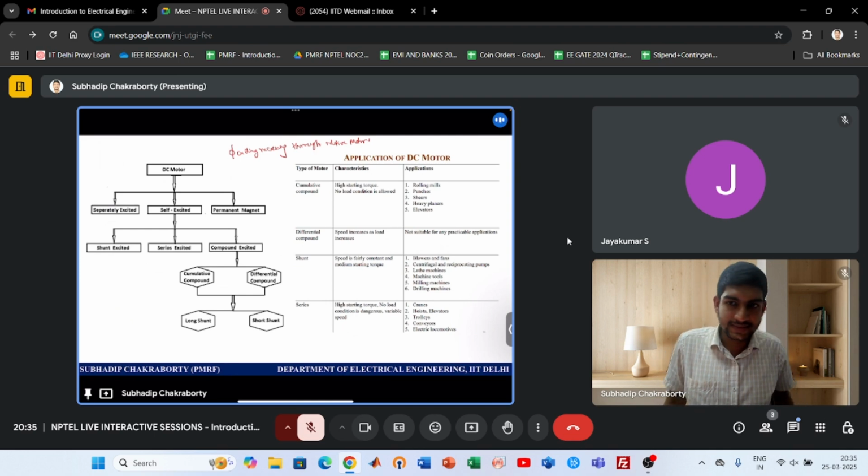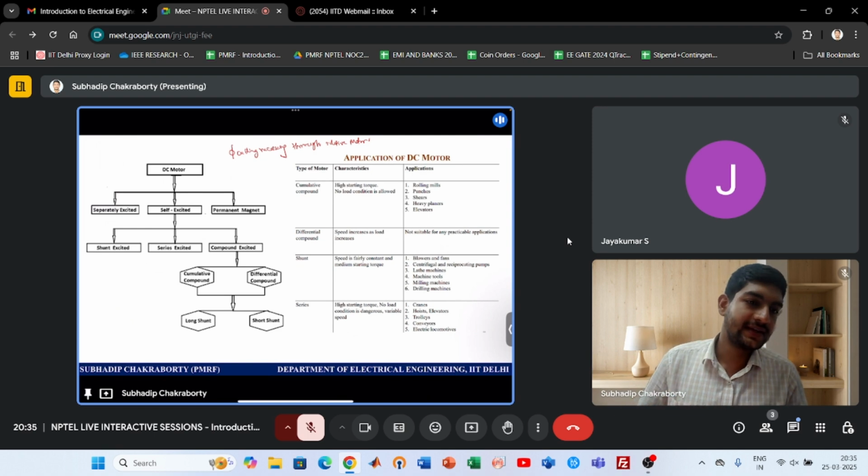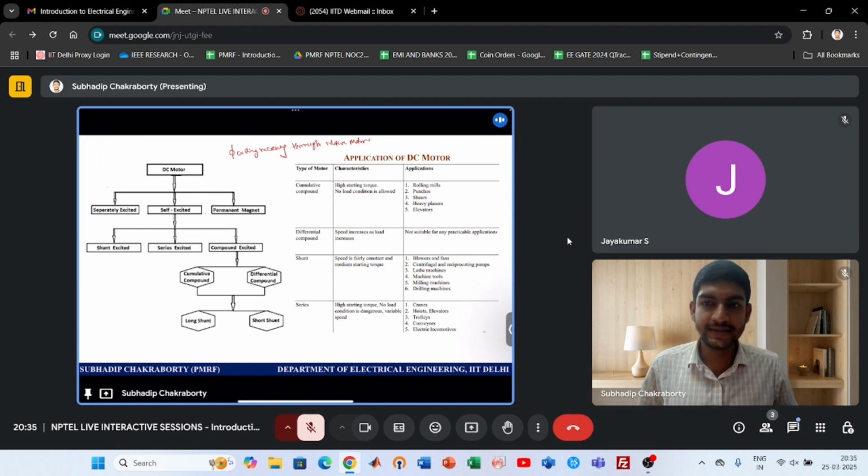That's why we rotate the conductors in the armature, so that there is a relative motion. If there is a relative motion of the conductor, even for a fixed flux, the voltage is generated. That is how the voltage is electrically generated, by the motion of the conductor. Or in other words, by giving a voltage, I can generate the motion by generating the force. I told you how it works for the generator. But based on how the excitation or the flux creating media is designed, that declares the type of DC machine design. It may be separately excited, so the field coil is sitting separately.